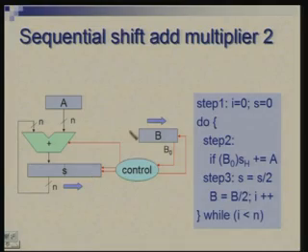So as partial products get added, one by one bits keep on entering the right half of S. At the same time, B this register is filled with value B, and as you shift right, it keeps on making spaces on the left side.